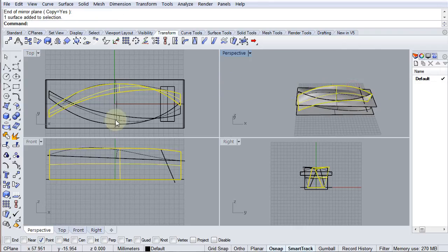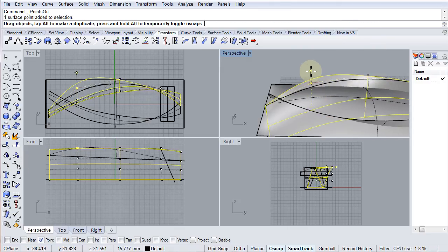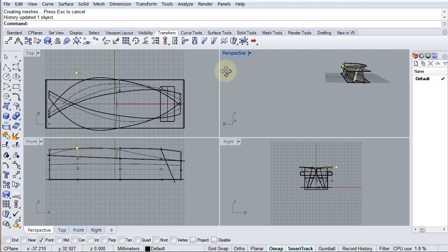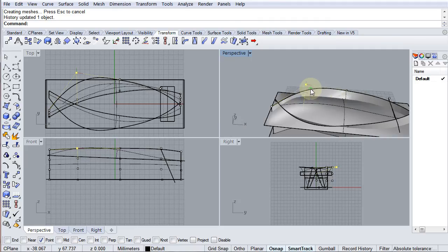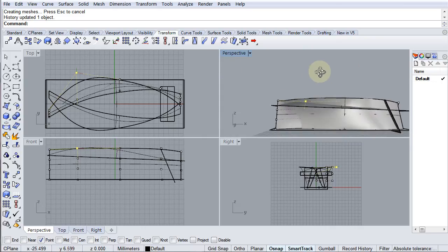This object here is the master, so if I turn on the control points for that object, and for the sake of argument pull that one out, you'll see that it's reflected in the opposite side. So if you were to do that without history on, this one would change, but this one wouldn't. When you have the history recorded for that motion, for that alteration, that transform, it will carry over the action onto the other one, which can be a very, very powerful form of modeling.